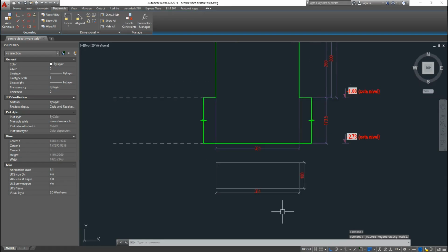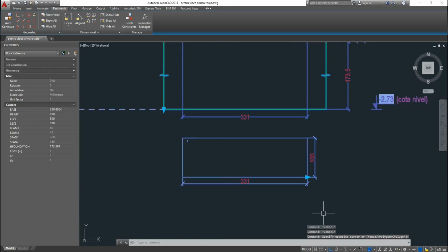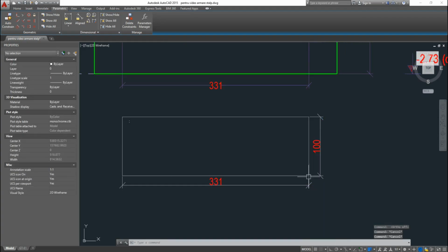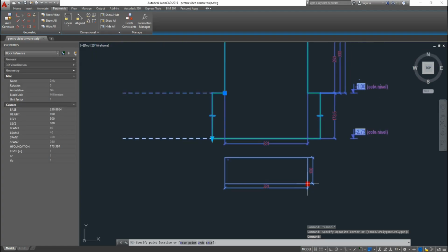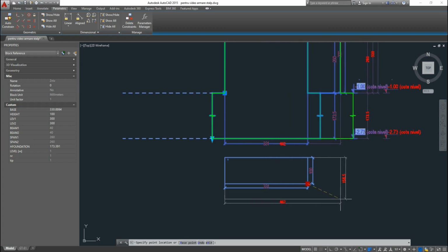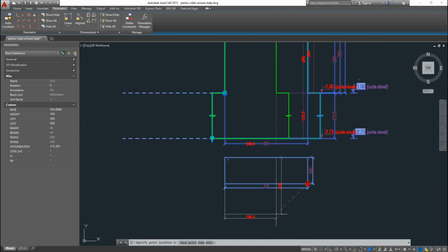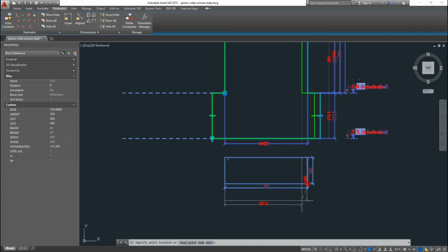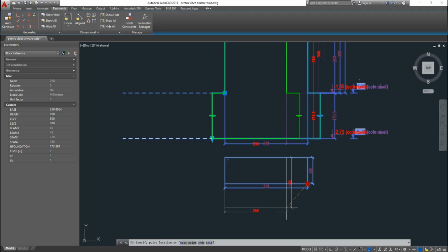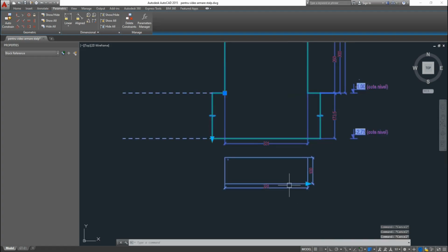It's just a cool effect. I'm choosing the block, I'm deactivating ortho to show you that having the same active heads, although it shows only one of them randomly, if we click on it, you can move the drawing bidirectionally all together. So we're making the stretch of the base, but we're also obtaining the stretch of the cross section on Y direction. Of course, it's not a precise dimension to choose for the column, but it's a nice effect with various applications in other blocks. Okay, so now going back,